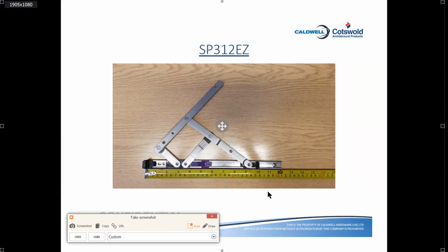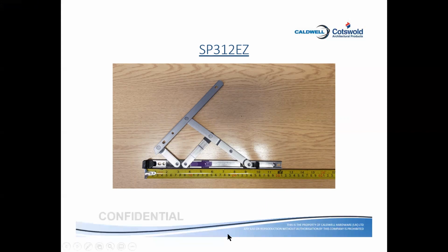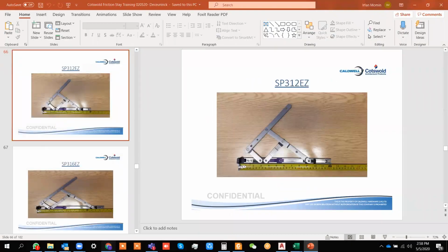In this, a latch or a button is given. By pushing this button beyond, you can take it to cleaning mode, and after that you close the window. Automatically the window will go to the egress mode, 90-degree opening mode, and clear opening fire exit mode. Because cleaning activities are once in a while, at that time you can just latch it from the top and bottom, and you can open the window. I will show a short video explaining it so that the concept is clear.